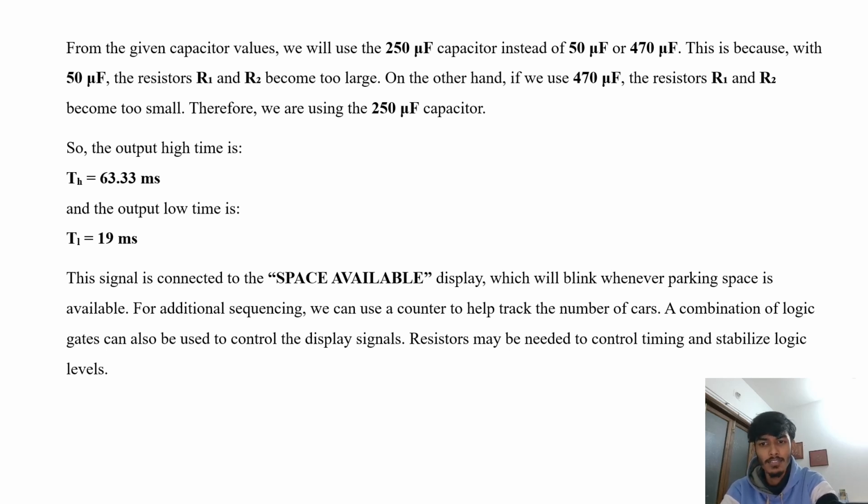Using the selected values, we compute the timing. The display stays on for about 63.33 ms and off for about 19 ms. That creates a clear blink that is noticeable but still smooth.